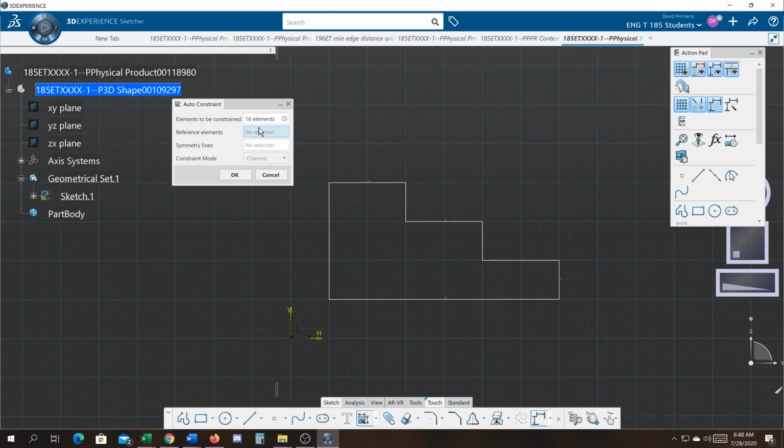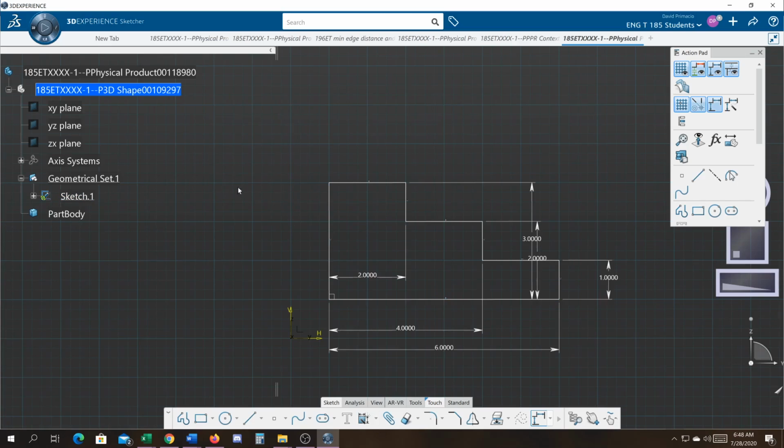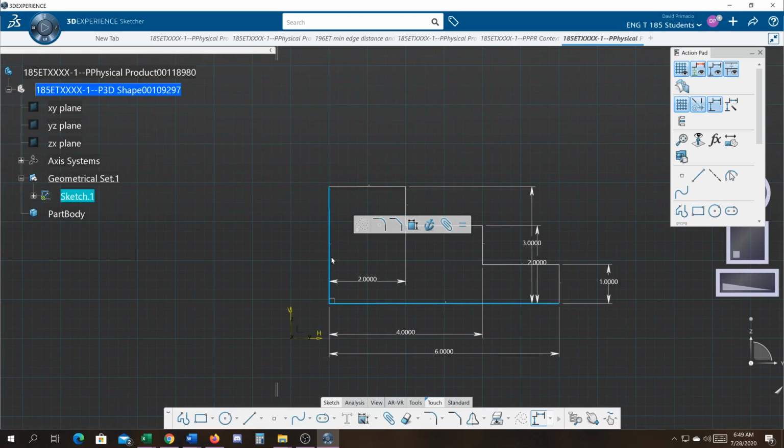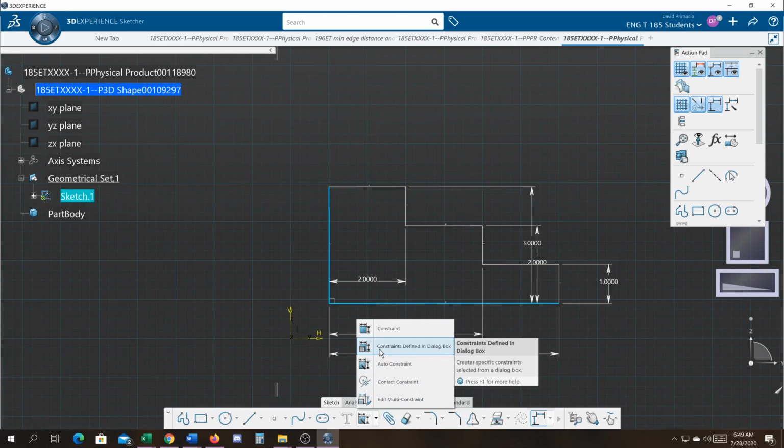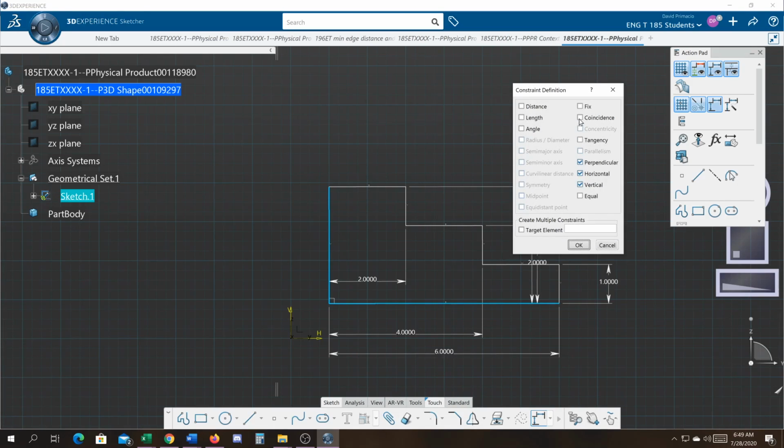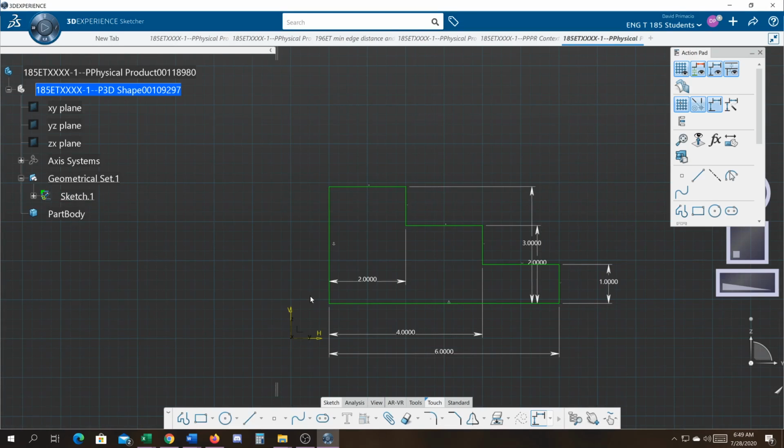I'm going to go to references and select my references. Stack dimension it and select OK. Grab this line and this line over here and set those as your anchors. Remember the H and V's, they got to go, they can't stay, so you'll have to use the other technique I showed you. To get an easier way to get rid of them all at the same time is go to the dialog box and apply your anchors and remove these horizontal verticals. Okay, then you just got to move the constraints out to where you want them.